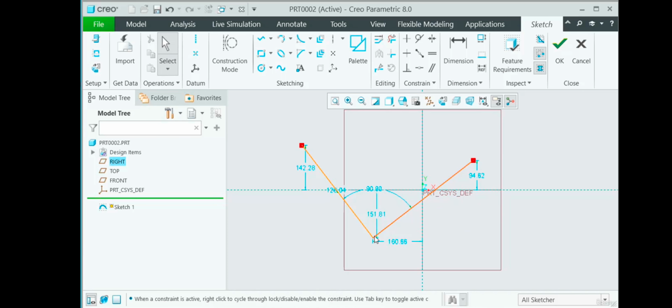So what it means is this line enjoys all the degrees of freedom that is available to it. Degree of freedom is the direction in which it can move. It can move or it can also rotate in 3D. Here, what we have to do is we have to restrict these degrees of freedom. And it can be done by using the concept called constraining. Constraining is restricting the degrees of freedom of an object. We can do this by the use of constraints.